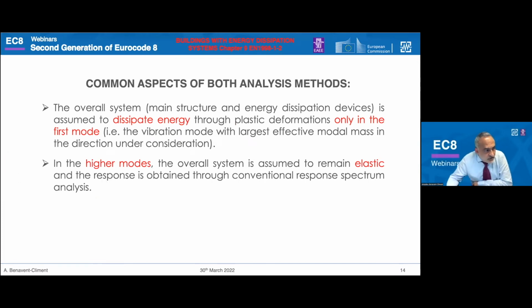So both methods have also in common the following aspects. First, the overall system, that is the main structure and the energy dissipation devices, is assumed to dissipate energy through plastic deformations only in the first mode. Only in the first mode. First mode means here the vibrational mode with largest effective modal mass in the direction under consideration, in the direction of the ground motion that is being considered.